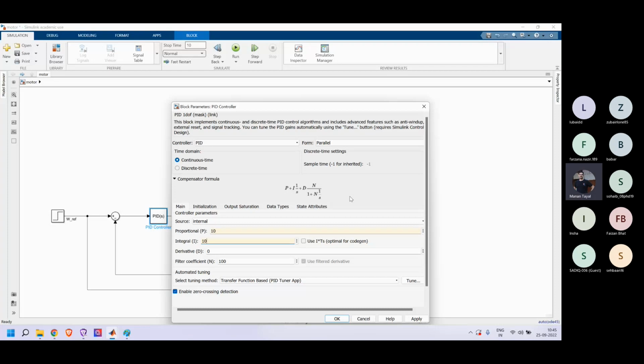A first order filter basically removes all the higher frequency signals and just gives me the output as low frequency variations. So all we want right now is to decrease the variations, so that my derivative term is in control, and I am able to get the benefit of this derivative term again, right?